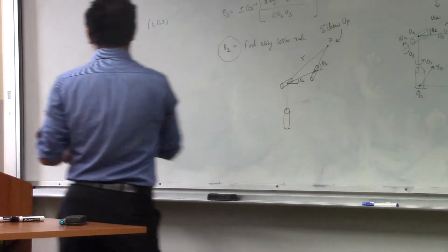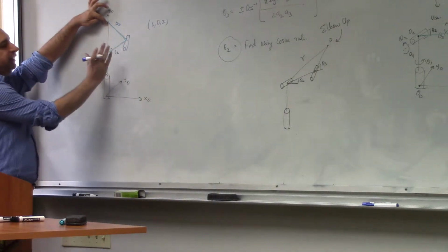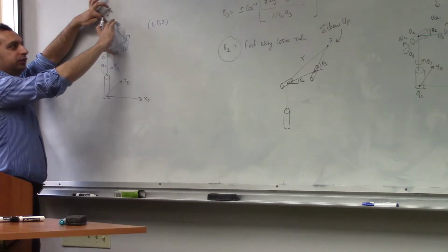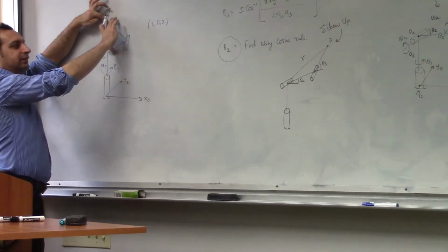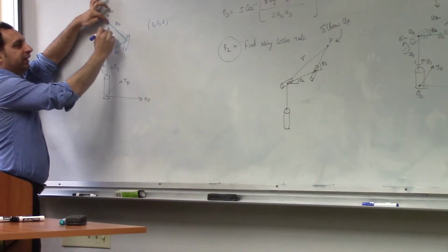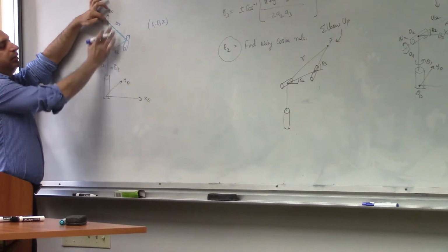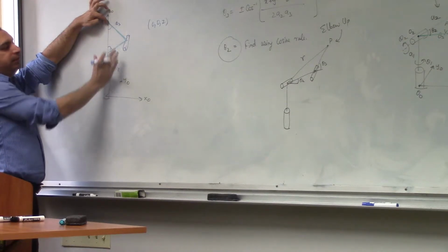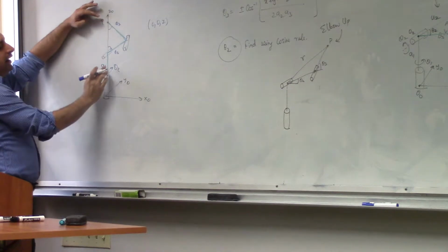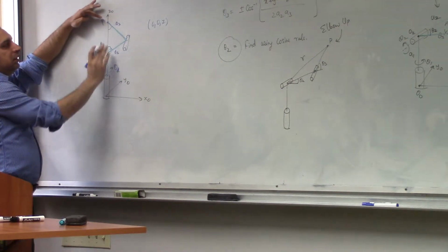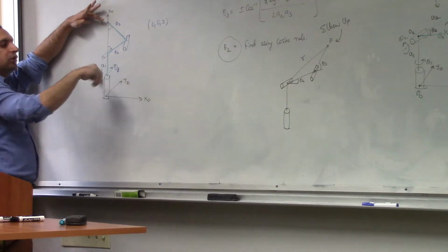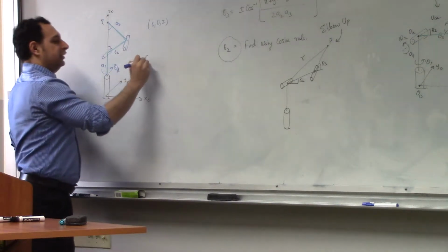So in this case, this point will remain constant even if the manipulator rotates along theta 1, right? If you hold these two constant at some degrees, let's say that both a1 is equal to a2, in that case this angle will be equal to this angle because the opposite sides of this triangle are the same. So if I hold them constant like this, and if I rotate theta 1, the point will remain constant and it will go around. So theta 1 will have infinite solutions.